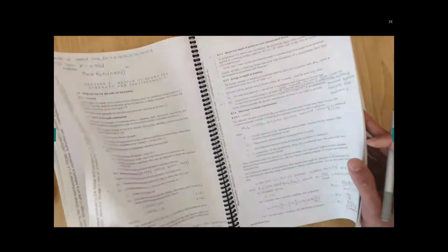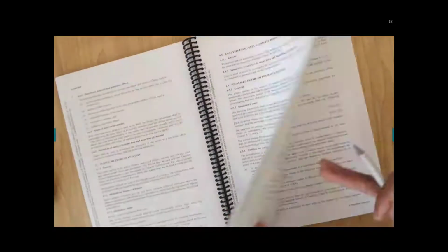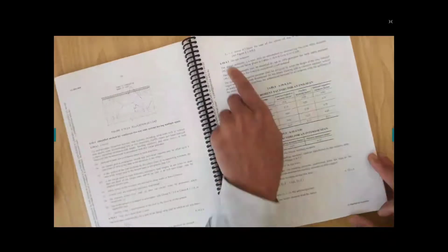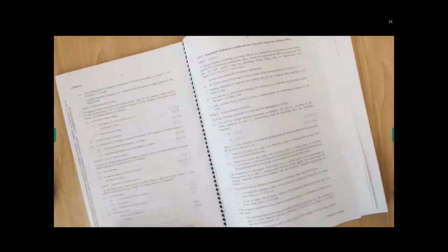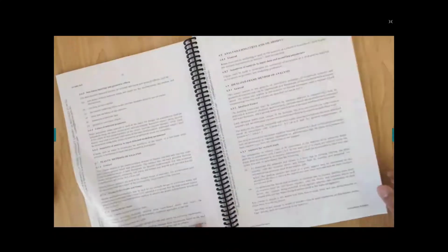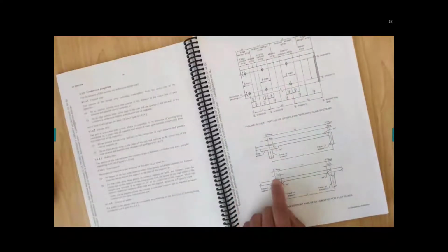I think it is in clause number 6. I think we discussed that one in the last class, but I can show it to you again here. In section 6 somewhere they talk about this L effective and all. Let me find it. Here you go, L effective, sum of this n span, also figure number 6.1.4b. So let's find that figure, 6.1.4b. Here you go, A support is just from the edge of the support to the center. So it's just like 250 in that range.